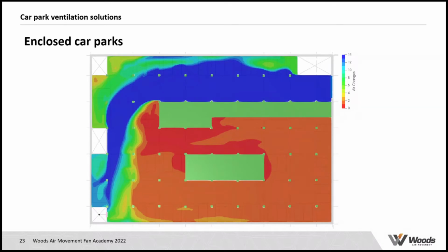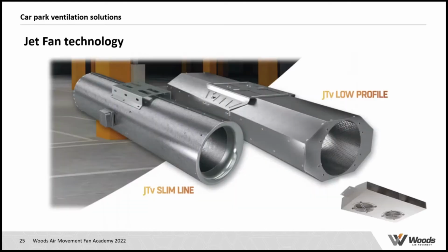So if we want to avoid the use of ductwork because of all the nuisance related to the high pressure losses turning into high motor powers required, we could consider another concept, a concept which was introduced in the mid-90s, around 1995, called the jet fan technology.